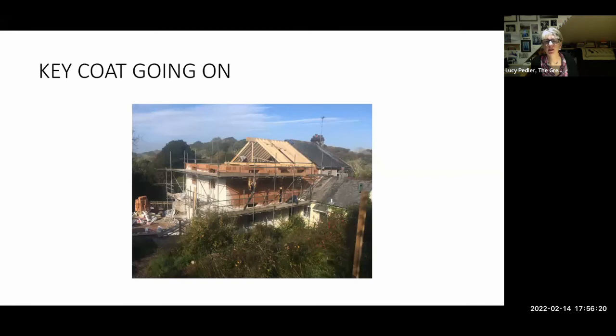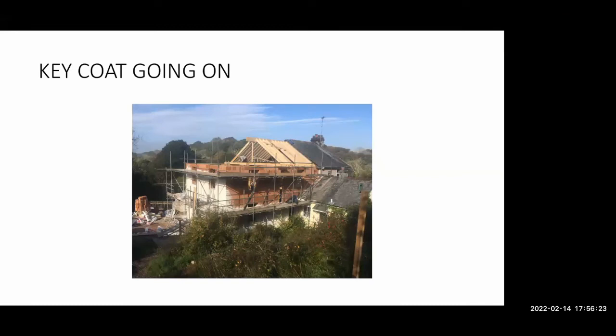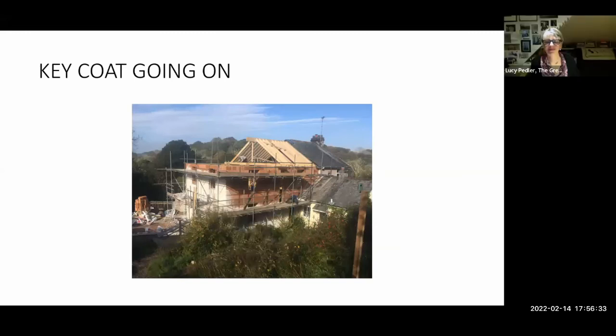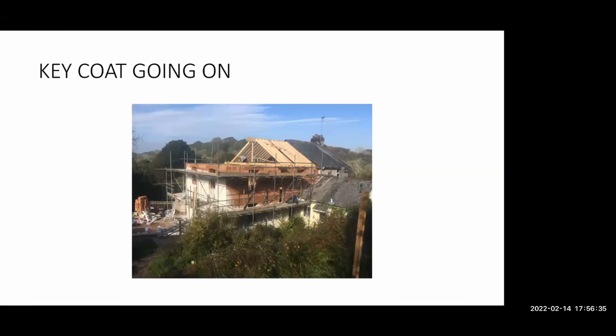It's about air tightness. It wasn't a question so much, but being a practicing architect and having architect friends in Germany and Austria, whom I've been visiting for longer than I care to mention, this is absolutely standard across Europe. Mostly they get their air tightness with render, probably a lime-based render, internally and externally. And if you're trying to approach Passive House, they will simply use 15, 16, 17, 18 centimeters of insulation externally, and use a thin render on top of that.